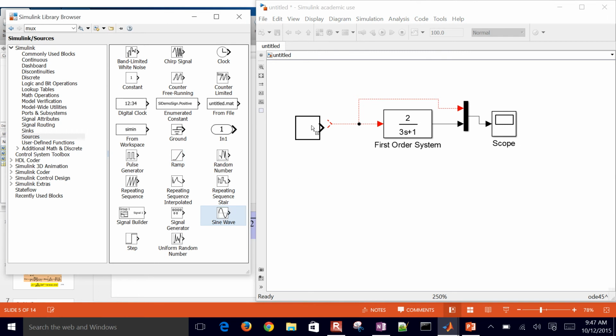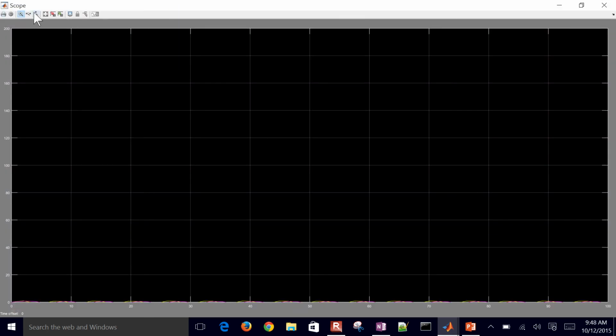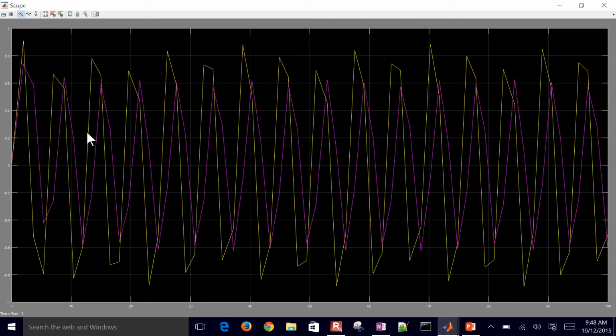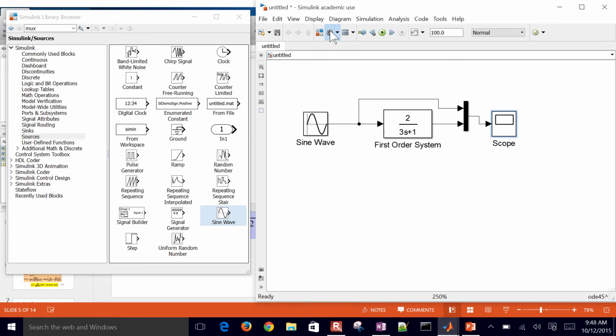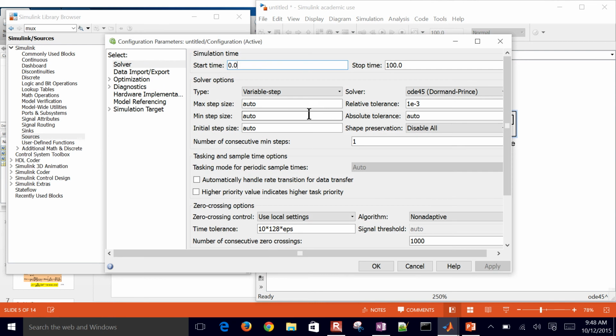We can put anything we want in there, let's say a sine wave, for example, and then we'll see the scope. Let me readjust this. You can see here, in Simulink, it looks a little bit jagged. We may need to change our integration step size. So I'm going to come in here to some of the options, and let's see, max step size.